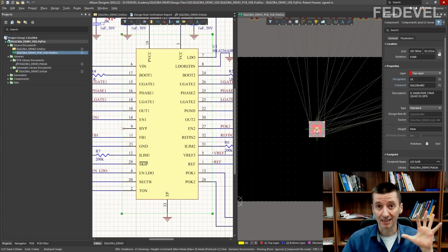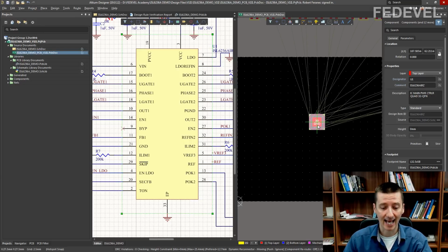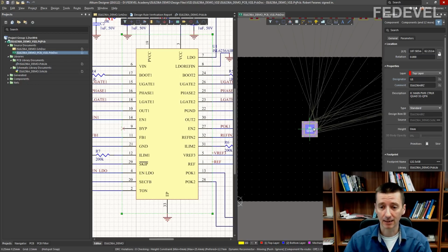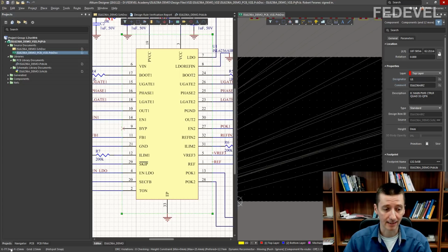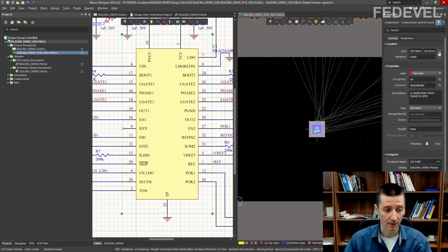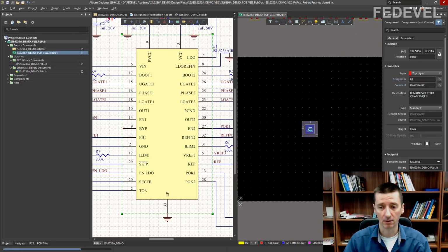At this moment, because it is red, it means it is going to be placed on the top of our PCB, but we would like to place it on the bottom. So to move a component on the bottom, press L on your keyboard. Okay, now it is on the bottom, and place it exactly into middle of our board. So watch X and Y position and place it into 25 by 25, like this. Left click.